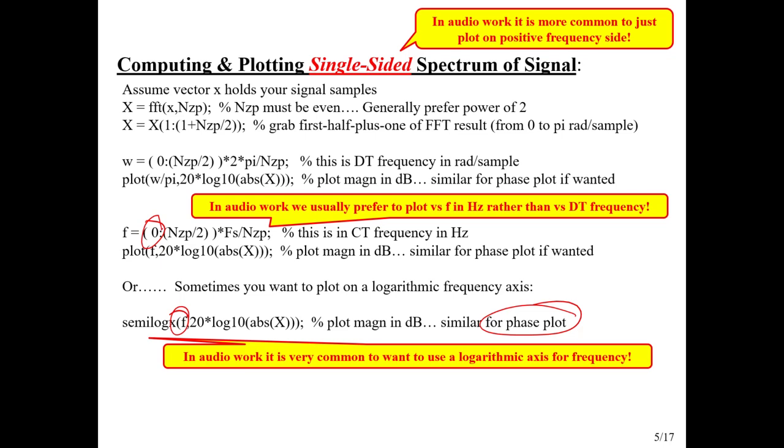And so it will just discard that point, but it'll give you a little warning on the command line. So when you're running commands in a function or a script file, always go look at what's going on back at your command line, because MATLAB will give you warnings. It won't stop your work, but those warnings might tell you that you're doing something not quite right. But you might see that warning, like in this case, and say, yeah, okay, that's perfectly fine.